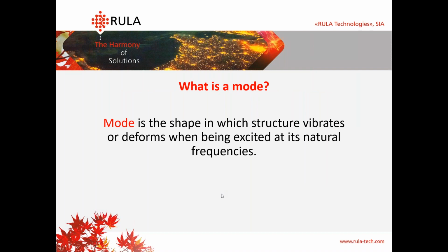So let's talk a little bit more about the main definitions for modal analysis. The first one is called mode. Mode is the shape in which a structure vibrates or deforms when it's excited at its natural frequencies. Under typical operation conditions, a structure will vibrate in a complex combination which consists of all available mode shapes, and we will discuss all of them.